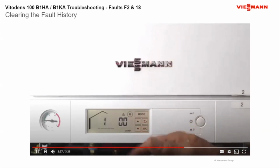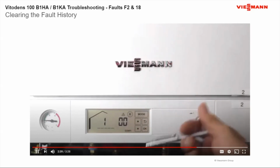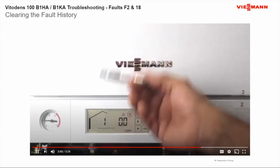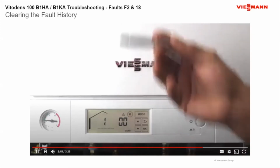So we fix the problem, we go in here and clear the faults, especially after new installs, because sometimes we create a bunch of different faults. Like that OB is a flow issue, or it could be that we had air in the system on a new installation, but they never went back and cleared the fault on the boiler. So make sure all the faults are cleared before you leave, after you fix the problem.